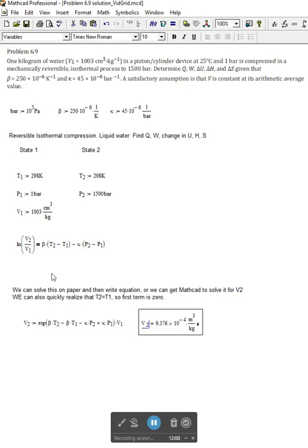So there's several equal signs. There's the colon where you're assigning something. So we use that when we assign constants. We use a colon when we assign an expression to a variable. There's the bold equal sign, which is just used as a definition. We aren't actually calculating anything specifically here. We're just telling MathCAD this is an equation.